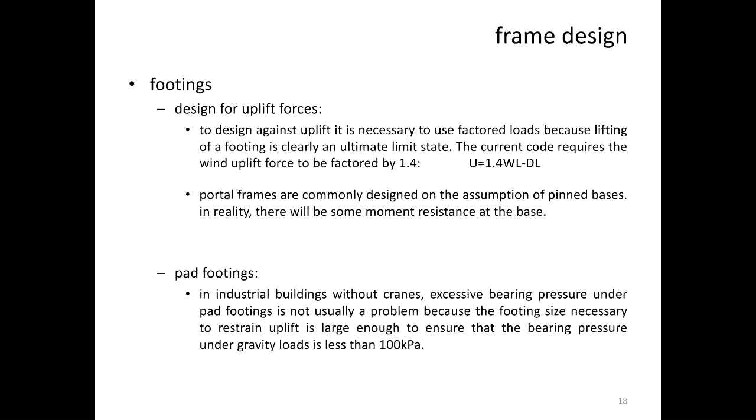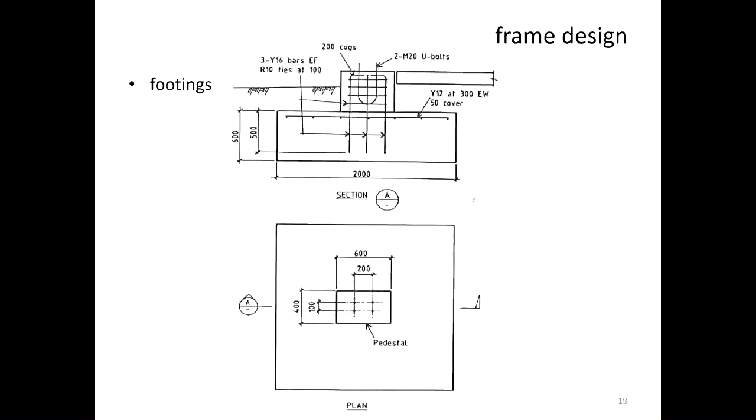If you're building on very, very bad soil, then in some cases you have to have piles into the ground. I'm actually not sure what they have used here, but the drawings have got pads and a pile option, which means it's not a good site. If they've used piles, generally it's not a good site. If you've used pads, then it might mean it's a much better site. I'll finish the footing pad and then give you a short, quick break.